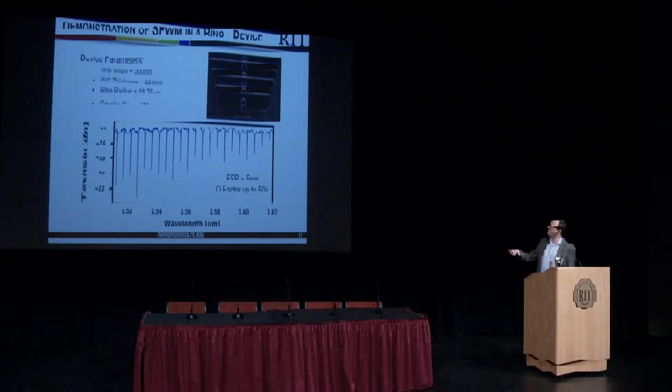So we've been working on this for quite some time now, so I'm going to show you some of our early results just to get you into what we're doing, and then the challenges that we're trying to essentially solve with this. So we have a chip with waveguides and individual ring resonators, so that's looping a waveguide on itself. Here are the parameters for the sizes, and there's a very small gap between the rings so the light can couple in. Whenever the wavelength is a multiple of the circumference, you have these resonant dips that you see essentially right here.